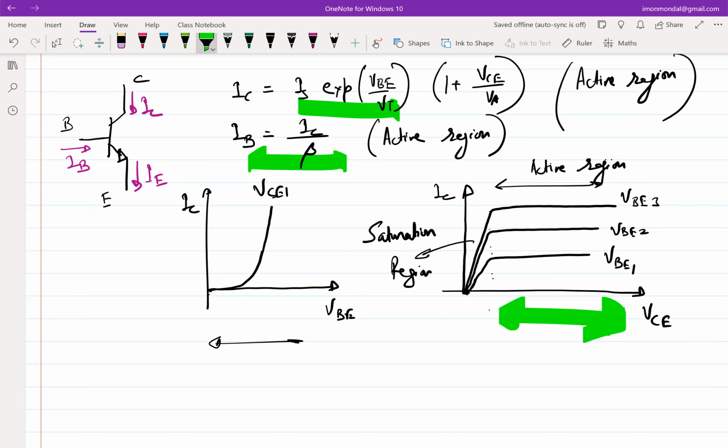But then something else happened. We didn't talk about this, but there is another phenomenon called velocity saturation that happens in MOSFETs. If you reduce the channel length sufficiently small, then the pinch-off doesn't happen, but the maximum velocity with which a carrier can go gets saturated. So that happens in this region. Then again, people started calling it the saturation region. So essentially the naming is checkered. I'll not get into who gets to name what. That is more than technical.